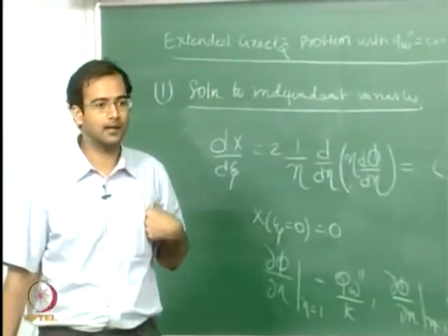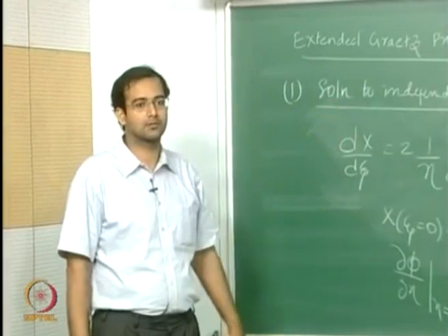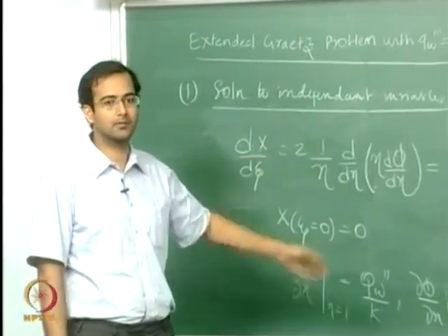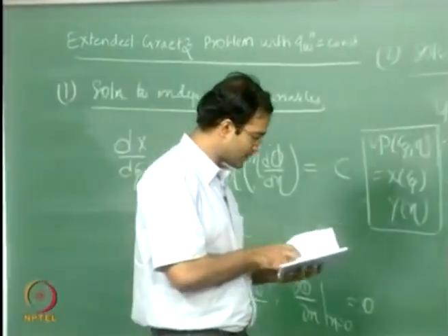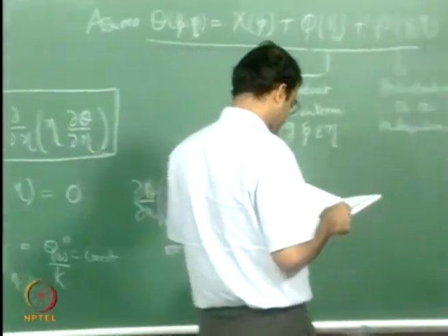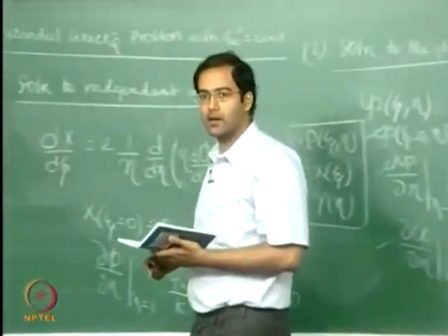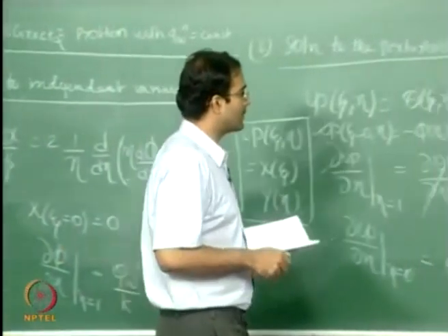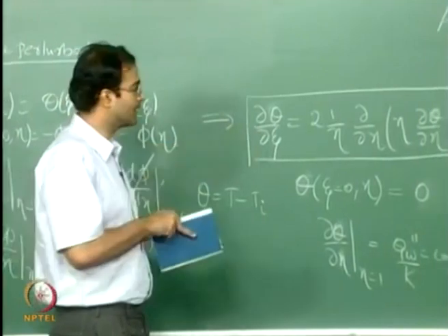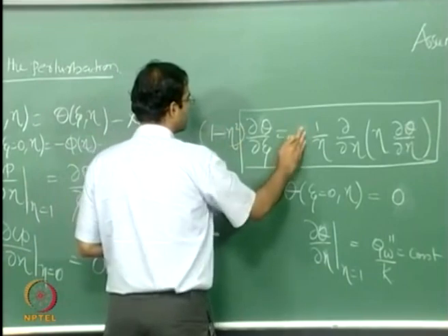Please go through that, and in the assignment I will ask you to do the parallel thing for the duct flow also. Only thing there, you have cosine and sine, here you will be getting it in terms of Bessel functions. The final solution was done by Sellars, and Sellars did both the case where you have a plug flow as well as the case where you have a parabolic flow. In the case of parabolic flow you have 1 minus eta square which is coming here. When you substitute for the velocity profile you have 1 minus eta square and there is no 2 here,